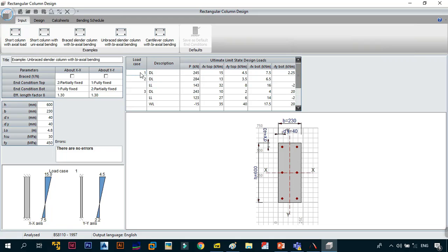So in this case, load case 1 has the DL, so all these loads in this column will be for load case 1. Then for load case 2, everything in these two rows will be for load case 2, because for this one we did not put 2 or 3, so it just assumes we are dealing with the previous load case that you specify, but it will not associate it with load case 1 because there's a 2. The same applies when you come to load case 3, as you can see, where you have the DL for dead load, live load, and then the wind load.